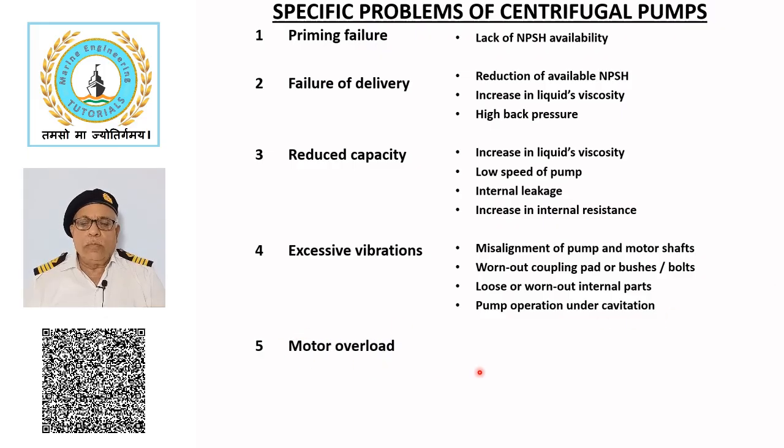Motor overload. Cause of the motor overload may be due to higher density or viscosity of pumped liquid. Viscosity can be reduced by heating, which can also reduce density to some extent. Otherwise, pump should be operated with reduced flow.